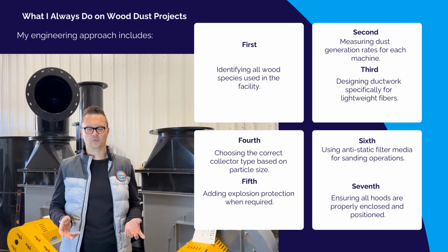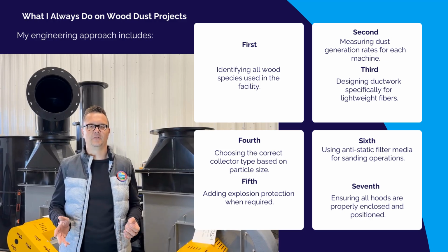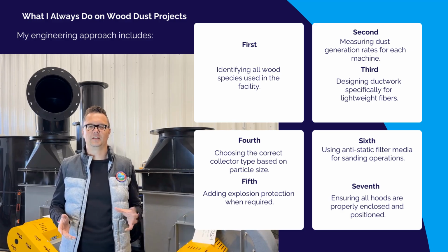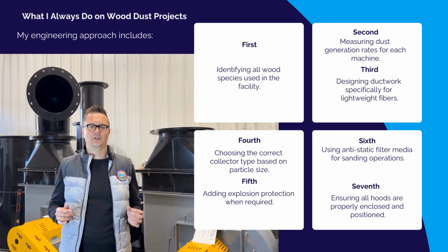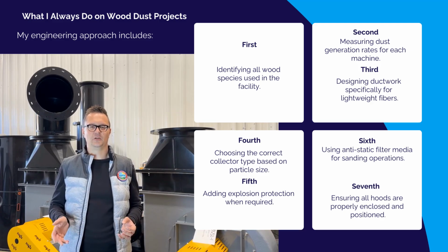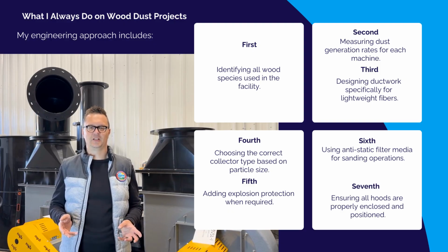What I always do on wood dust projects. My engineering approach includes: first, identifying all wood species used in the facility. Second, measuring dust generation rates for each machine. Third, designing ductwork specifically for lightweight fibers. Fourth, choosing the correct collector type based on particle size. Fifth, adding explosion protection when required. Sixth, using anti-static filter media for sanding operations. Seventh, ensuring all hoods are properly enclosed and positioned. These steps ensure safe, clean, and compliant dust control.